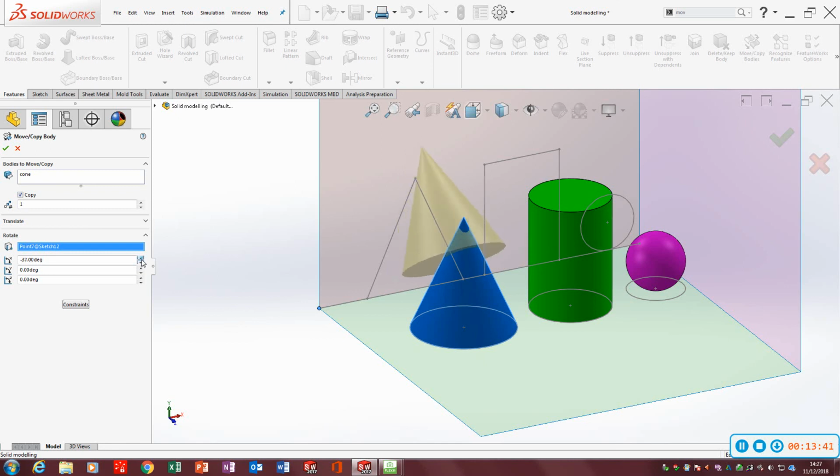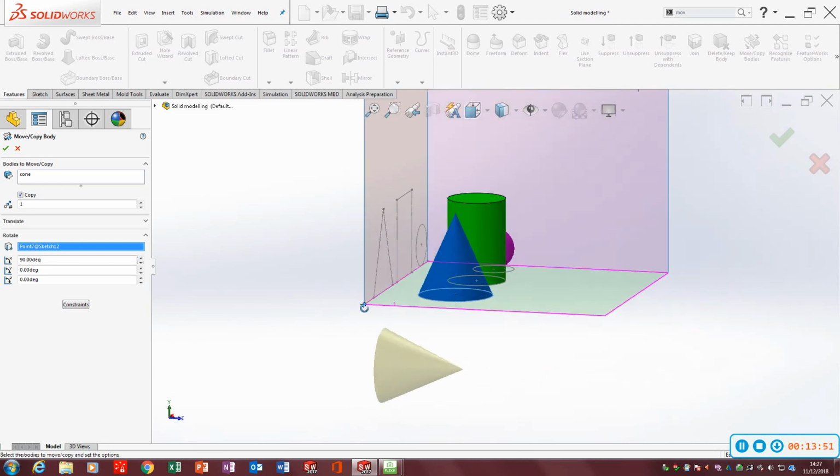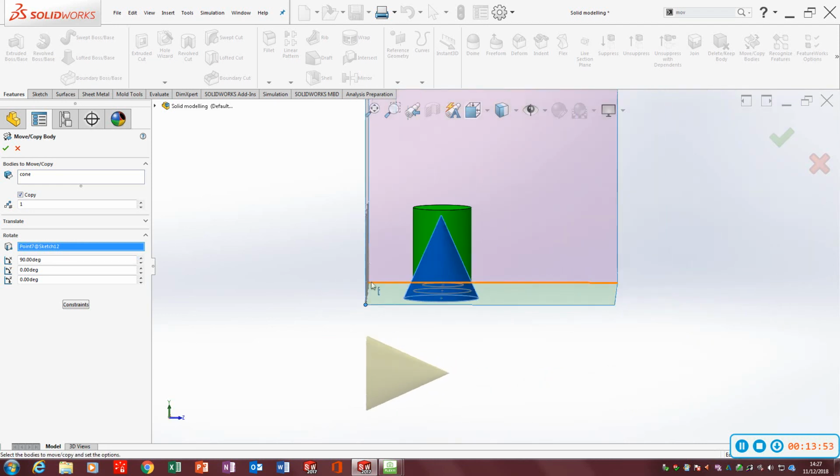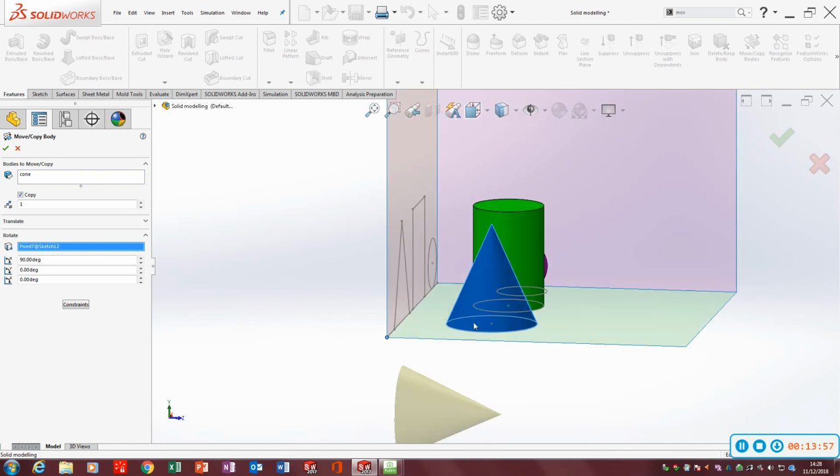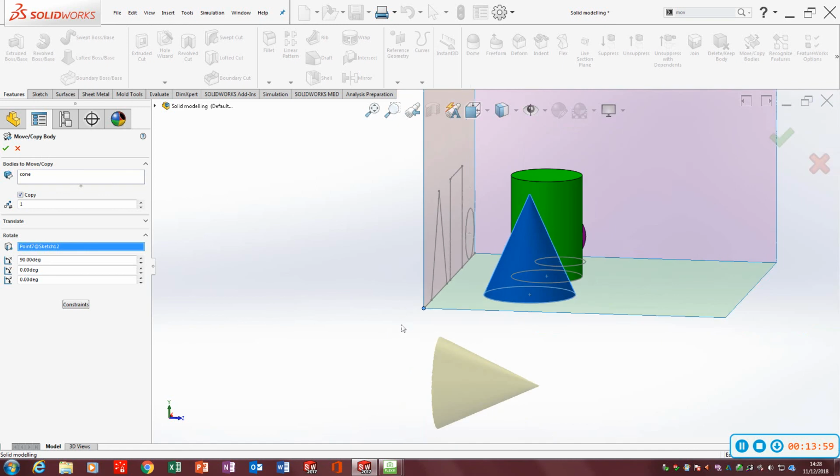I'm going the wrong way. So I'm going to rotate that until it's 90 degrees. So you can type in 90 there if you want. Alright, and notice the way it's just gone back with the feature there. Press F there if it goes out of the way. It's gone back to the vertical plane, but I have no issues with that. Okay, I'm going to click OK.